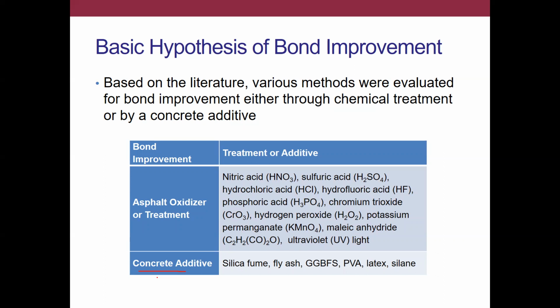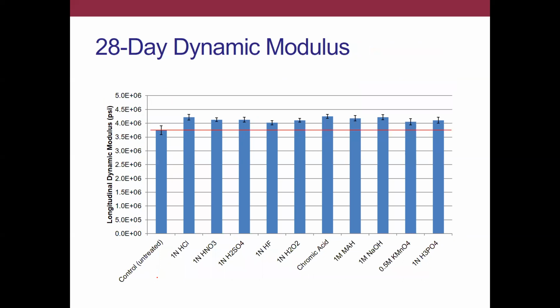these oxidizing treatments. When we did those treatments to our RAP, and then made various mortars and measured the dynamic modulus of those mortars, we indeed did find improvement relative to our control, which in this case was normal, untreated RAP. We did not do a control of a virgin aggregate because it would just be very much off the scale.